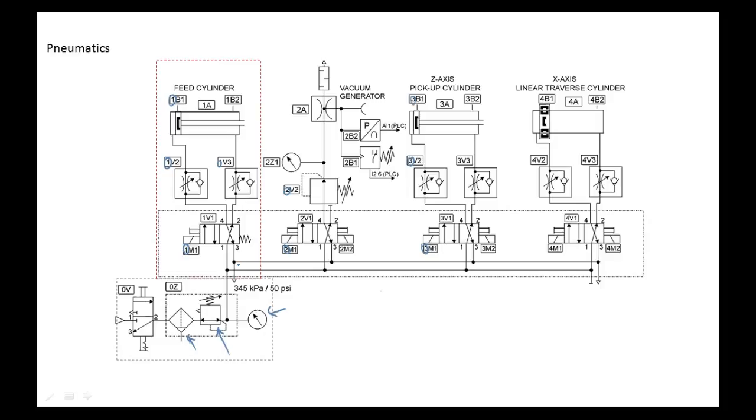In fact, they label some of these, when we go in and look at parts, as 5-way valves. But I didn't find any on the diagram that showed 5 ports. We can definitely look at the Festo, though. We'll look at the Festo, and they've got some 5-port valves. But what does a 5-port valve have? It has 2 exhaust ports.